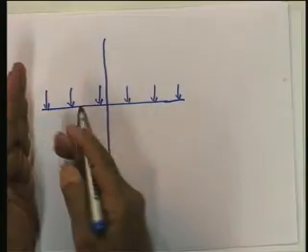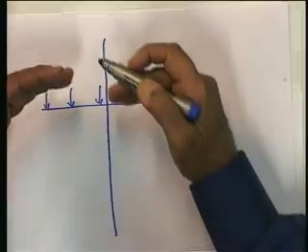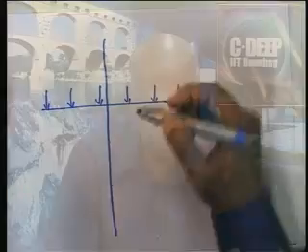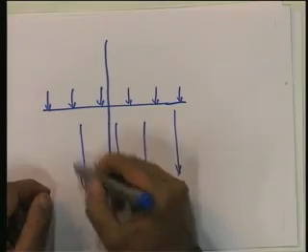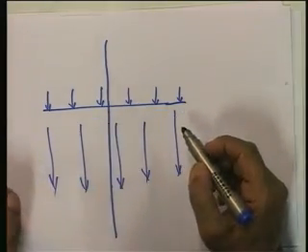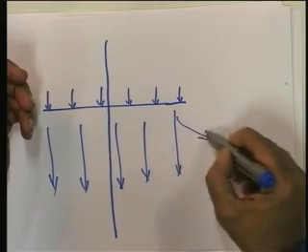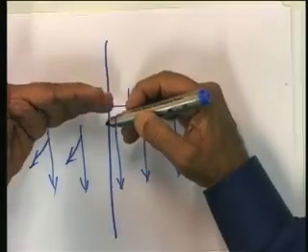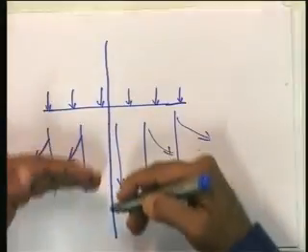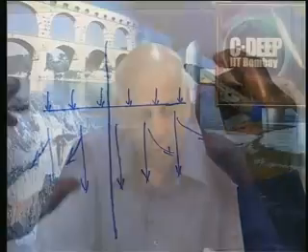In a similar way, when we have a very large area subjected to a uniformly distributed load, then for all practical purposes the movement of the water in the saturated clay is essentially in one direction, or another way of putting it is, even if the water gets expelled like this, the movement of the solid particles is essentially in one direction, that is in the direction of the load, and this is known as one dimensional compression, or more often one dimensional consolidation.